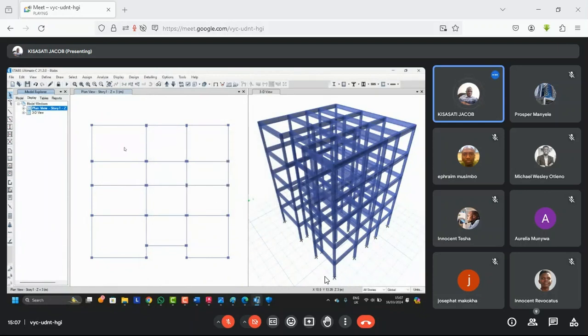After this, okay, let's try and define the slab. When I come here, this is the tool for defining the slab, the quick draw floor, this one. Make sure you use this one because we want to draw them quickly. So quick draw floors, this one. If I click this one, of course, we'll have to select this one, then select your slab like this. So if I start drawing, you realize nothing is actually happening. So we have to do something.